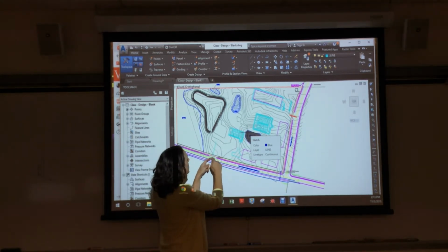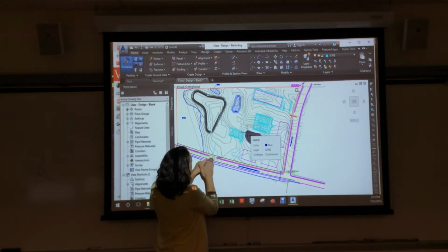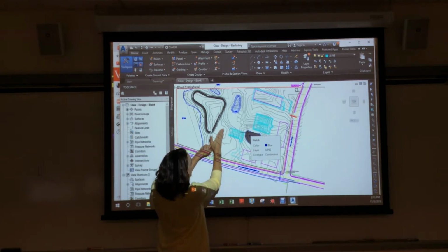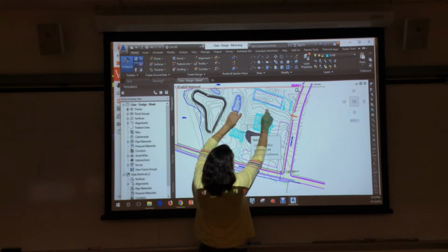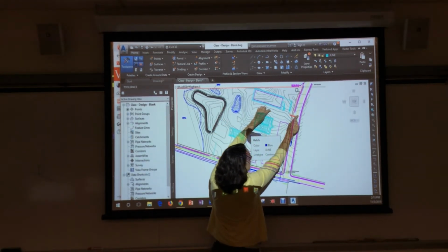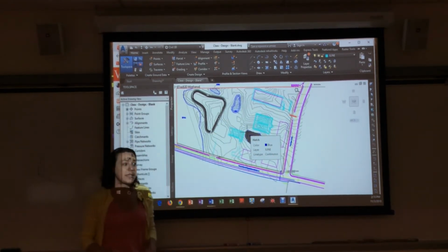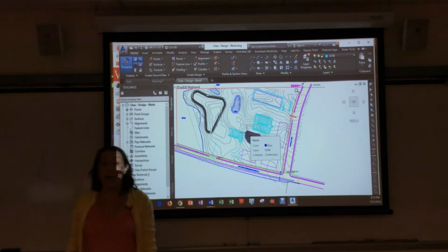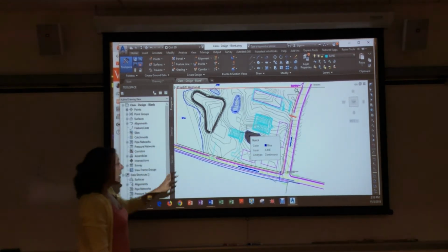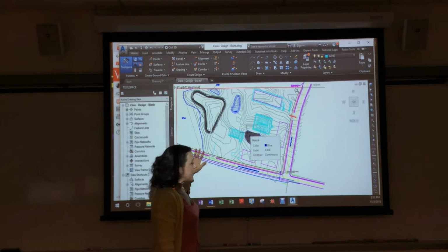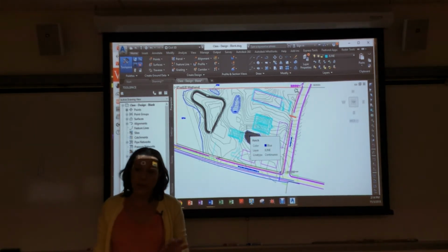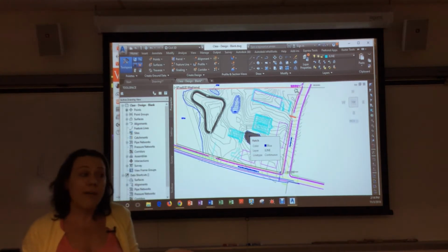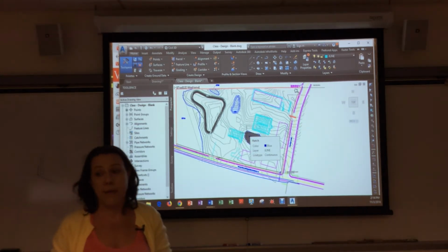This pipe system here wouldn't have enough capacity to take all the water from the road. So what you can do is put a high point here, make it go downhill and come back uphill and put a low point here, come downhill, low point here, come back up. Does that make sense? Yeah, because this is a DOT road, and DOT will not let us put extra water on their roadway because the storm pipes don't have capacity.